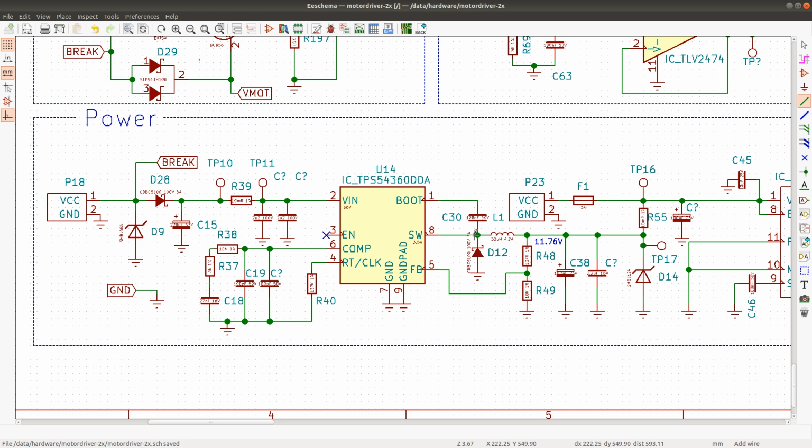So there can be a corner case where this voltage actually gets stuck at the input voltage, which would be 48 volts, for example. And I had this problem before, but the cause was that I mistakenly chose a diode that had a voltage rating below the required rating for running at a certain supply level. So what happened was that the diode latched up, and things got really out of hand.